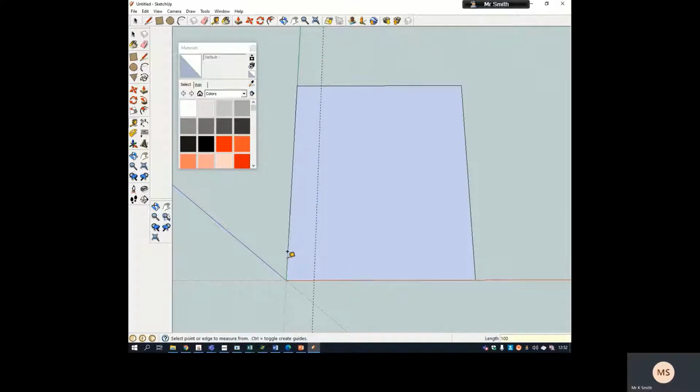So what I did here is I clicked on the line, the outside line, and then dragged across and then typed in 100 into the length, and I do the same on this side. So drag in, type in 100, and then click enter, and it'll find that spot for me. And the curve, it's almost like a circle, but it's only like a half a circle. So again, if I drag up now, instead of typing in 100, I'm going to type in 50. I know that my curve is going to go between there and there.